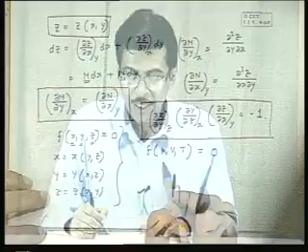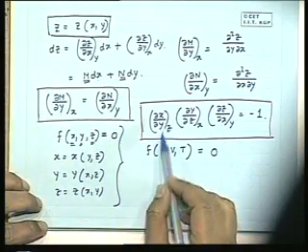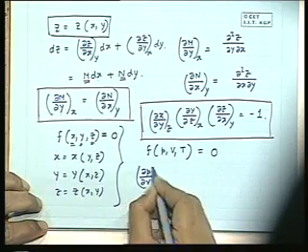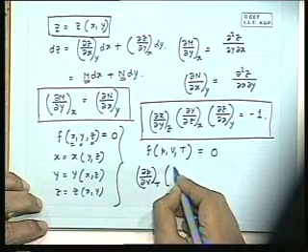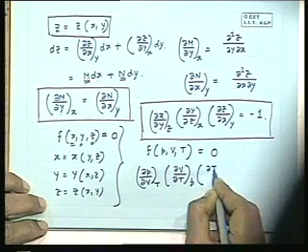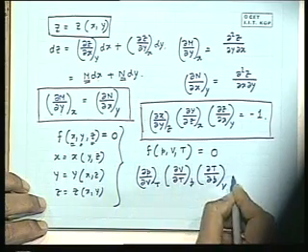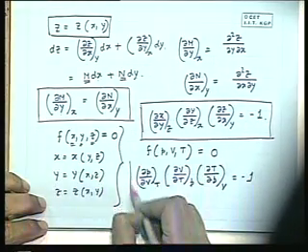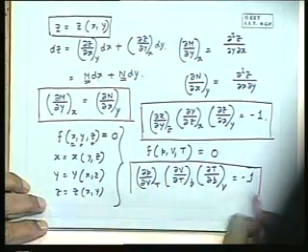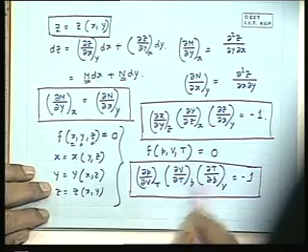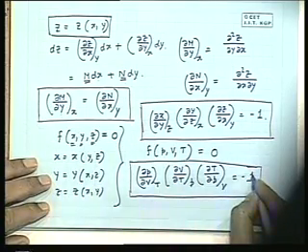So therefore, an immediate application of this mathematical theorem tells us that (del P/del V) at constant T, into (del V/del T) at constant P, into (del T/del P) at constant V, is minus 1, which is again a very important relationship, because this is derived using this mathematical theorem for our thermodynamic property relations. Sometimes this is known as the cyclic relation, del P del V, del V del T and del T del P. So this is one of the very important thermodynamic relations.